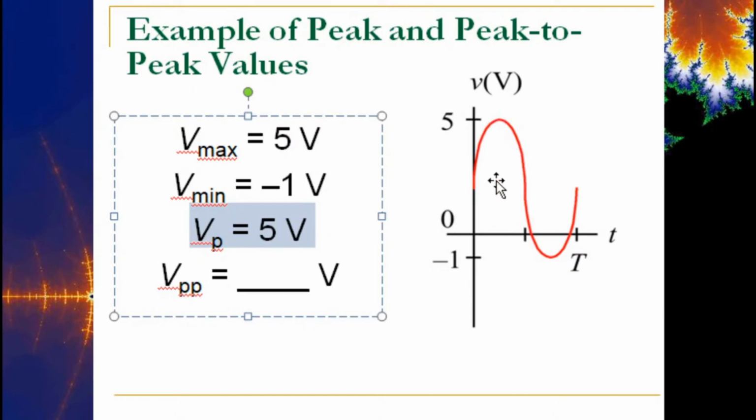That's okay, Ben, no problem. So in this case, even though if we pulled this down, this is 6 volts peak to peak. 5 minus a negative 1 is 6. So a peak voltage on something that averages 0 would be 3 volts. This will be shifted down 2 volts. If you shift this down 2 volts, that goes down to 3. If you shift this down 2 volts, you get to negative 3. So you'd have from 3 to negative 3. But it rides up here on this, apparently that's a 2 volt offset.